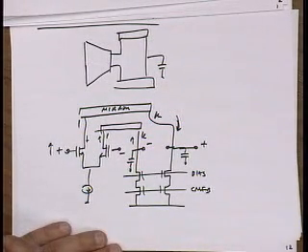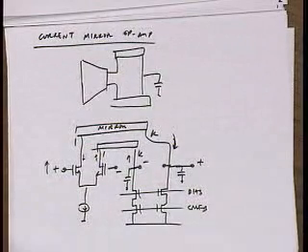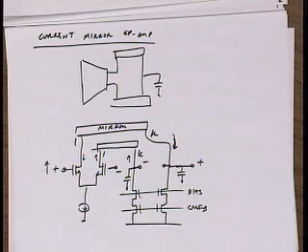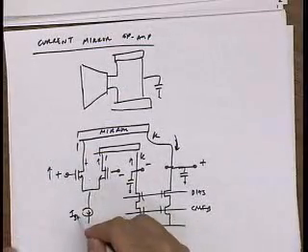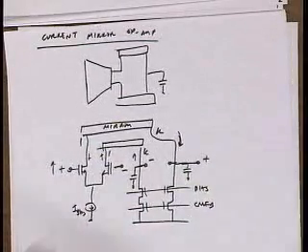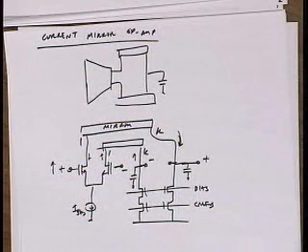Okay, why is this potentially better at slewing than our folded cascode? Anybody? Except Amin? All right, Amin, you have some ideas? I think you have a current gain of K, so K times more current gets to the output. Yeah, it's very simple. I have this mirror that multiplies my current, I bias by K, and so slew rate is proportional to current. Great.